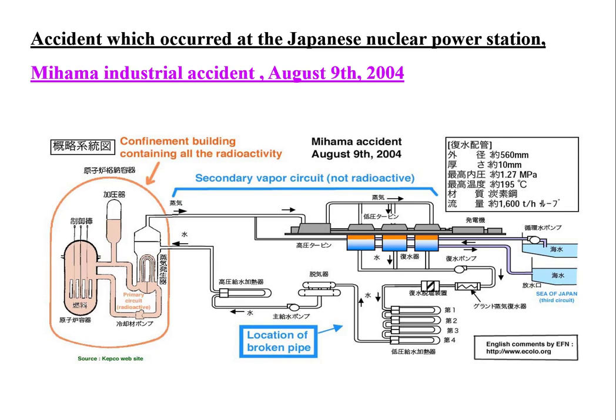The lesson we can get from this accident is to apply the proper inspection procedure and to ask why this thinning is even happening. The pipeline is not compatible with the media inside the pipe, to avoid that thinning.